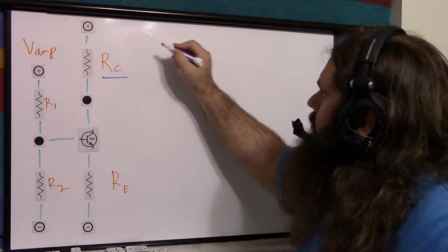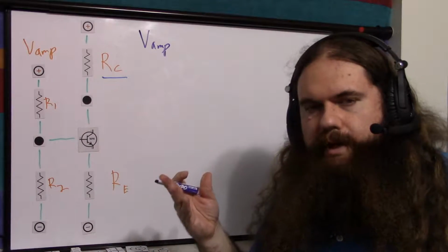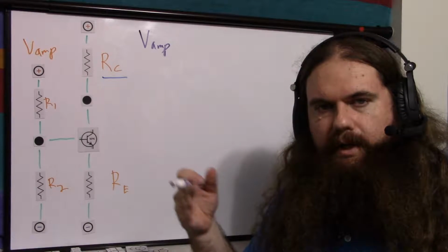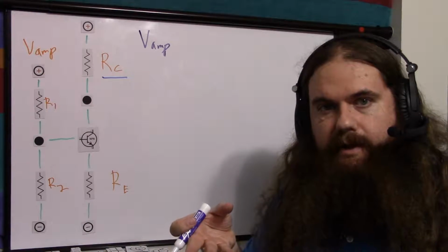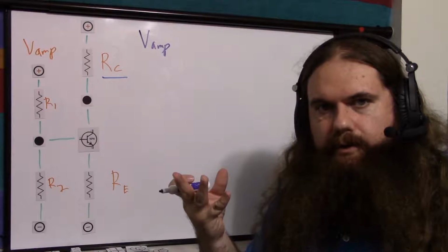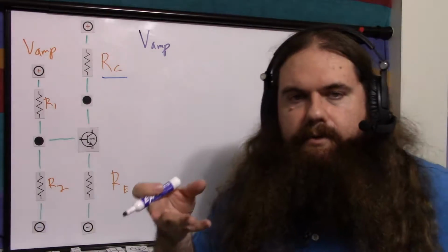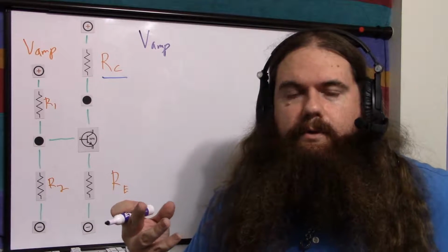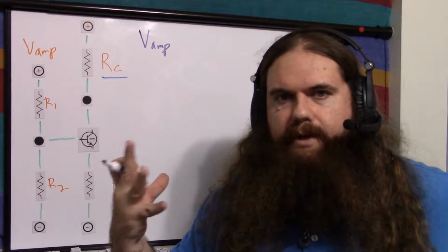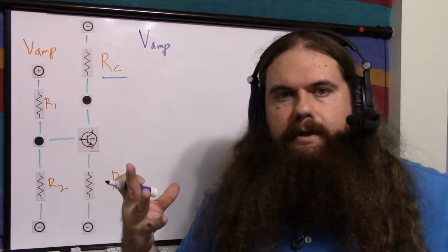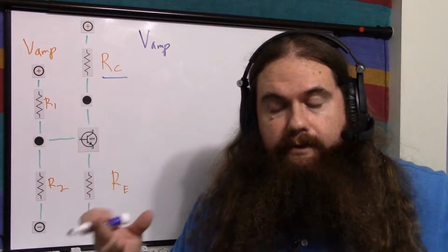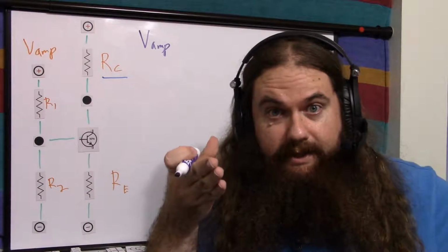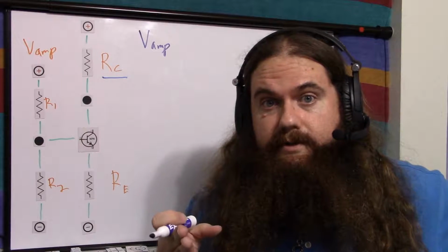So once again, you choose your V amp. Whatever power you have or want to supply, just pick the nearest available wall wart, or if you're going to buy one, just decide: 9 volts, it's not a very big speaker, maybe I could get away with 5 volts. Or if you're trying to drive a big ol' subwoofer or something, you're going to want maybe 12 or even 24. You've got to have some power through there, which means you need big transistors and resistors as well.